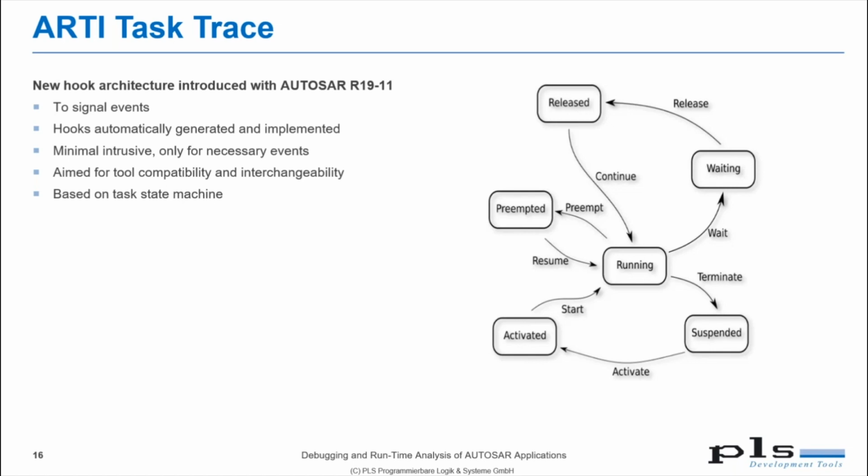With the work on the AUTOSAR standard, a new hook mechanism was implemented that is now standardized in AUTOSAR directly and does not come from OSEK anymore, and this makes it very lightweight. The focus was to make the hook mechanisms very lightweight and also standardized between the tools.